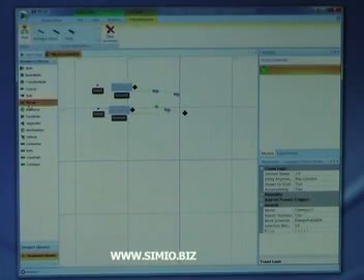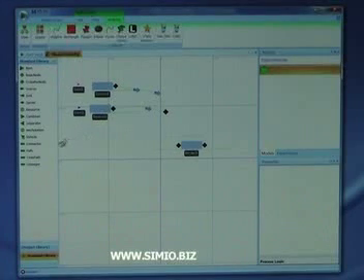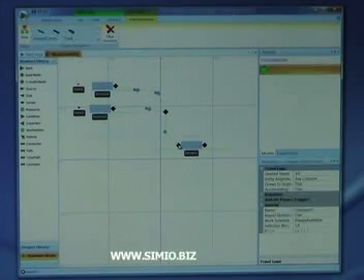Next, we'll place our server down. And then we'll draw a conveyor from the merge point into the server. Now the properties of the conveyors we're going to set through the property grid, just like we did with the sources.